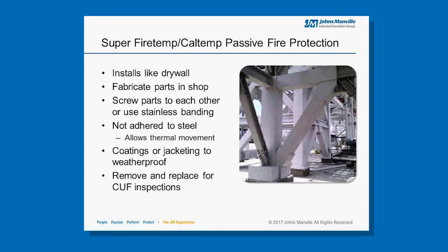Some of the keys with regards to Firetemp and Caltemp from a benefit standpoint are they install easy in any temperature. When you think about intumescent coatings or cementitious fire protection, those have to be installed in temperatures that are 40 degrees and rising typically.